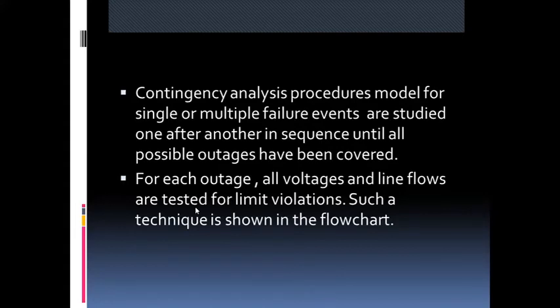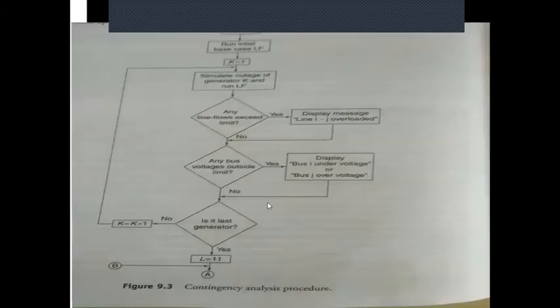See how contingency analysis will be done. Of course, it will be programmed. We use a simulation package, but you can study the flow chart and understand it. So initially, start, then all the parameters will be input to the system. Then you have to do the load flow. LF represents load flow analysis. Once all the system data is entered, you have to do the load flow analysis.